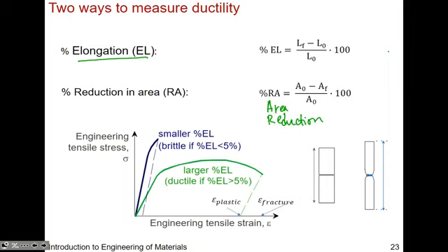And you've seen this before, right? You've seen the delta L versus L naught. That's just your strain. But now we defined it as if you were able to stress your material until right before the point of fracture, right before it breaks right here, okay, or right here. Right before that, and you trace back to where the strain would have been, permanent strain before failure, then that's where we define the strain for the ductility of the material before fracture, okay?